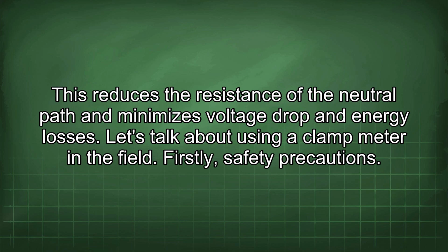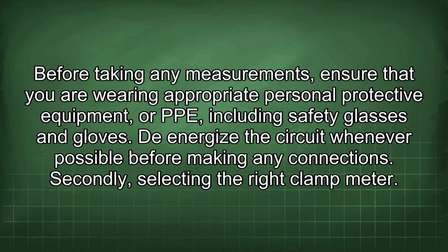Let's talk about using a clamp meter in the field. Firstly, safety precautions. Before taking any measurements, ensure that you are wearing appropriate personal protective equipment, or PPE, including safety glasses and gloves. De-energize the circuit whenever possible before making any connections.